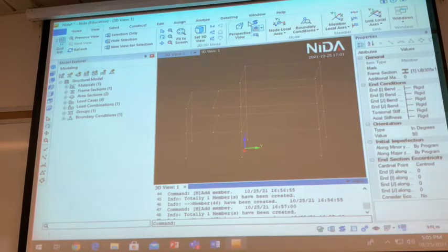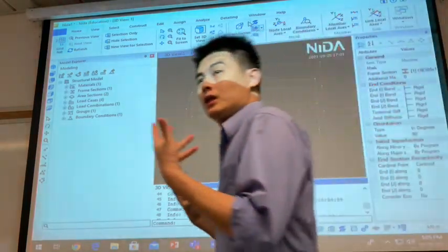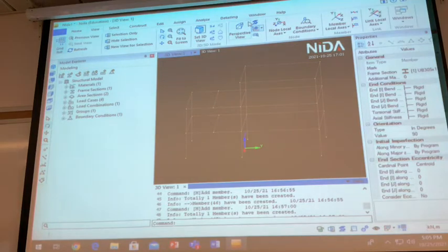Okay, has anyone done the geometry? When you finish the geometry, we go to the next step, because we have 5 requirements. Geometry is the first one. Now you have just set up the geometry, the connectivity between the nodes and the elements. Next, you need to define the dimensions or each coefficient.